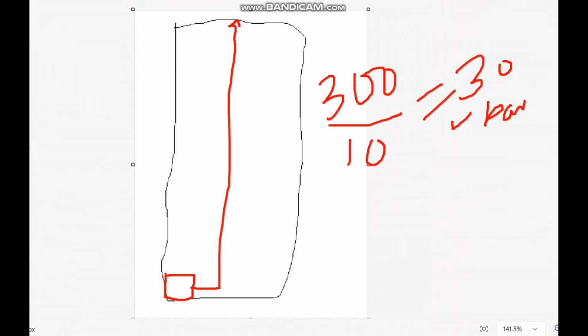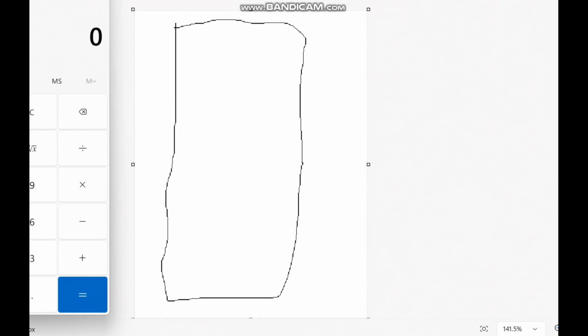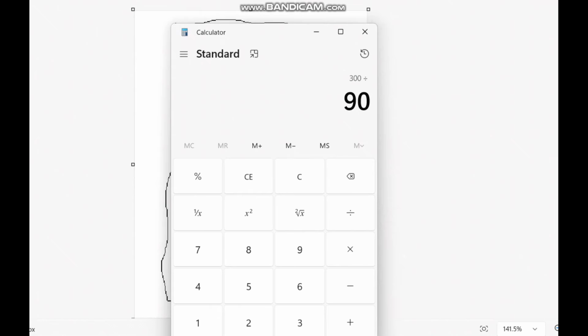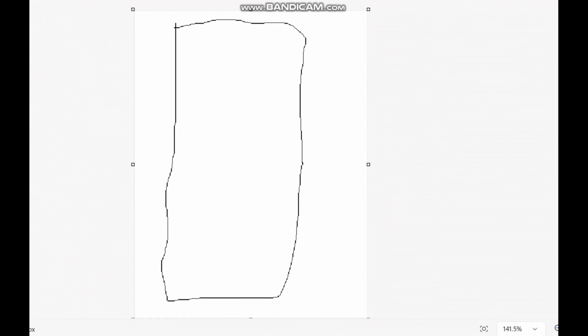And for example, if you go to a country like UAE, they have very strict regulation. Their consideration is, for any building more than 90 meter, you have to provide one mechanical floor. That is a rule in the UAE. For example, if you have 300-meter height, how many mechanical floors do you have to provide? 300 divided by 90, so at least 3.3 mechanical floors. That means 4 mechanical floors in the building. So you cannot limit to only one heat exchanger here. Additionally, there will be multiple heat exchangers in between.